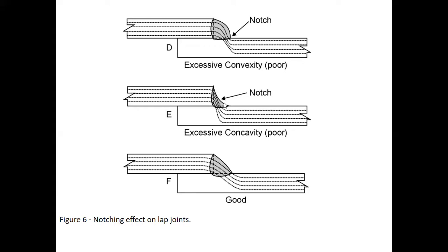This weld here could be created by dragging a downhand vertical weld down the joint. And it's not bad, it's smooth, it's got nice transitions. This one here is a little hard, but the weld size creates a lot of issue, because what happens is this plate is 3/8 of an inch wide and this plate is 3/8 of an inch wide. We want a weld with a 3/8 effective throat, so we don't pinch all those lines and bind them up